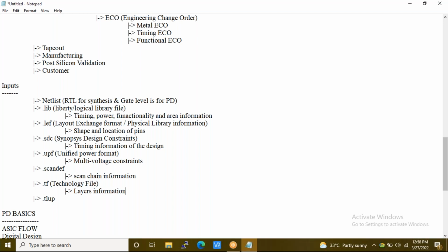Based on that particular current density passing through that wire, and also based on the external factors, the width of that wire, and all those criteria, they will be providing spacing between the wires such that they should not be shorted.